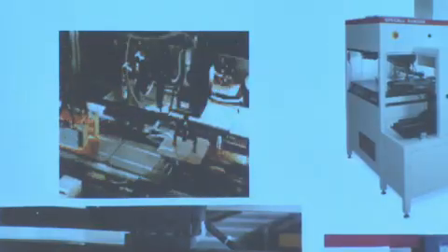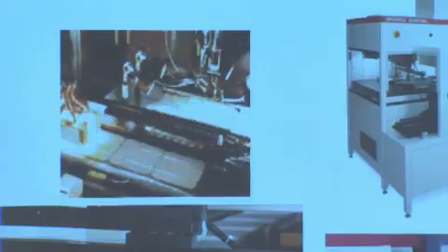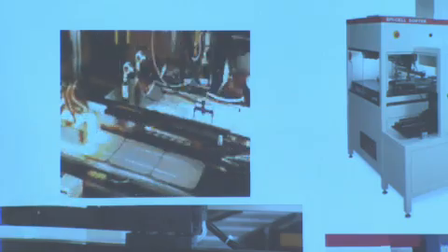and they're moving forward. And what you see right here in very low resolution are 2 probes coming down. This evidently is a 2-bus bar cell, not a 3-bus bar cell like this one. The probes come down and make contact with the bus bars. And the probes have multiple contact points so that series resistance along the bus bar is not affecting your measurement. Cell efficiency measurements are always tricky because depending on where you put your probes, your measurements are going to change because of the series resistance.